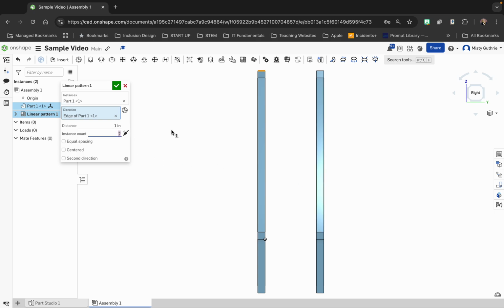Because humans are building these things and you have human error, it's always good just to have a little bit of cushion. In our case, our minimum is 2 inches, that inside dimension, up to a maximum outer dimension from here to here being 4 inches. I kind of like the more narrow bridges, but I don't want it to be exactly 2. So I'm going to do 2.5, and that gives me a little bit of cushion.